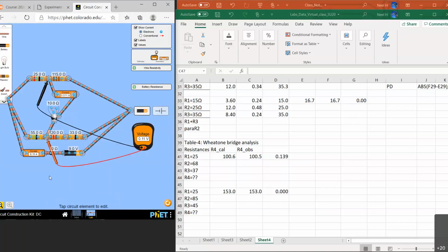Now again, you can see there's a voltage up here, which means I have to change the resistance on R4. Let's first get rid of 1 all the way to 0 and then see whether I can get the resistance from 1. Not possible, I need both of them. Change the second one on the fourth resistor until you see 0. It seems 2 is not enough, which means I have to add another, right? It's not a problem.